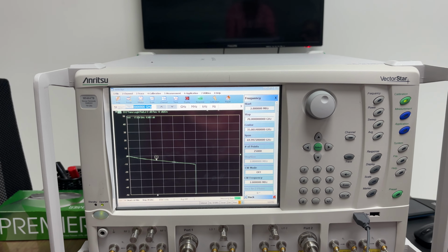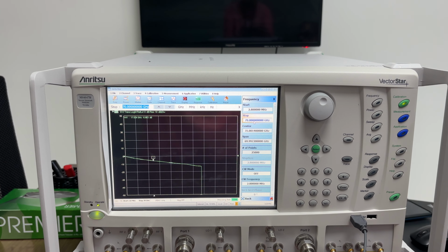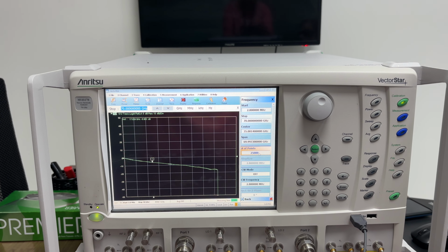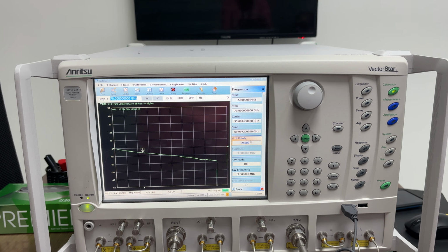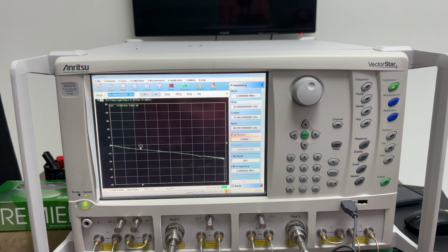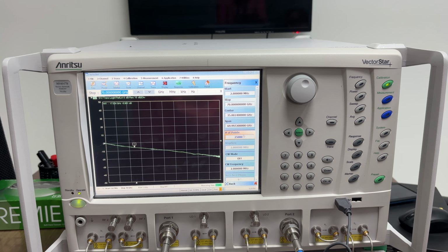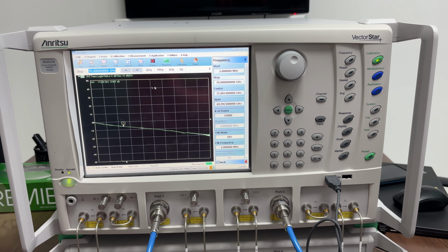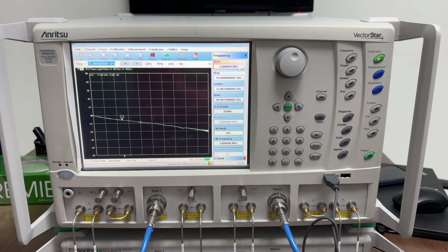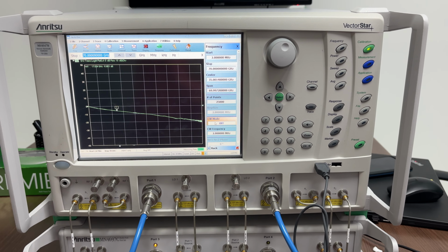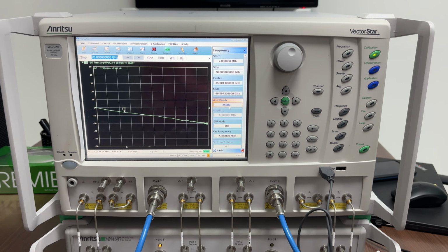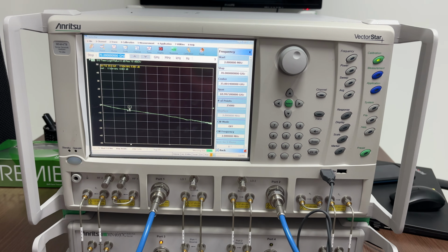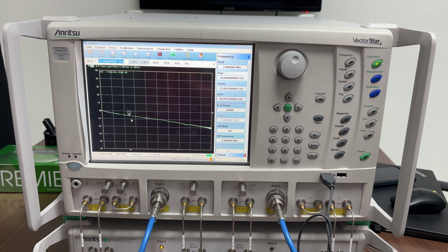As we are doing the measurements from 2.8 megahertz to 70 gigahertz, which is a harmonic frequency sweep for the 25,000 data points. We can have either 25,000 data points on multiple channels, or 1 million data points for one channel. So today we will be taking 2.8 megahertz to 70 gigahertz harmonic frequencies, so that we will be able to take care of measurements near to DC.